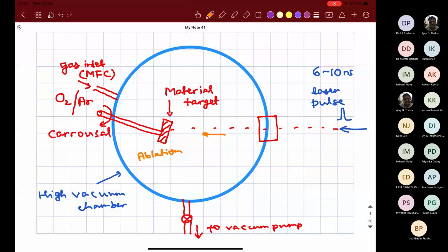And this will require striking with the air molecules present in partial pressure to form the plasma plume. And the environment is just right such that you can have a kind of assembly on which a substrate is placed. So this would be called the substrate. And at times it is preferable to put the substrate on top of a heater. The heater can go up to 800 degrees C or about 1000 Kelvin. That creates the right kind of environment for formation of film on top of the substrate.